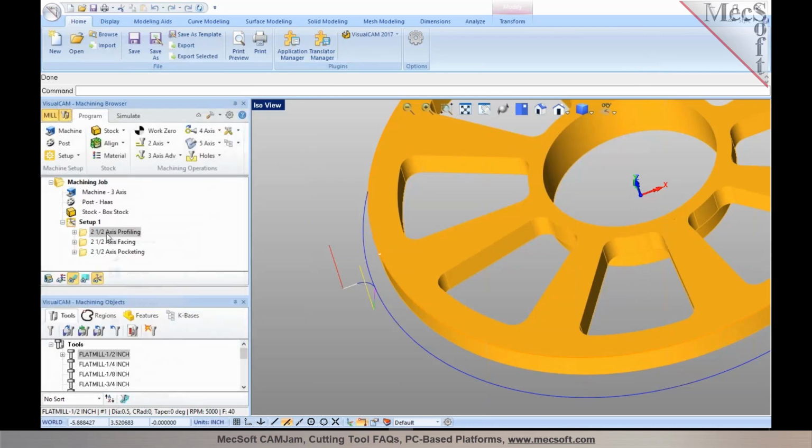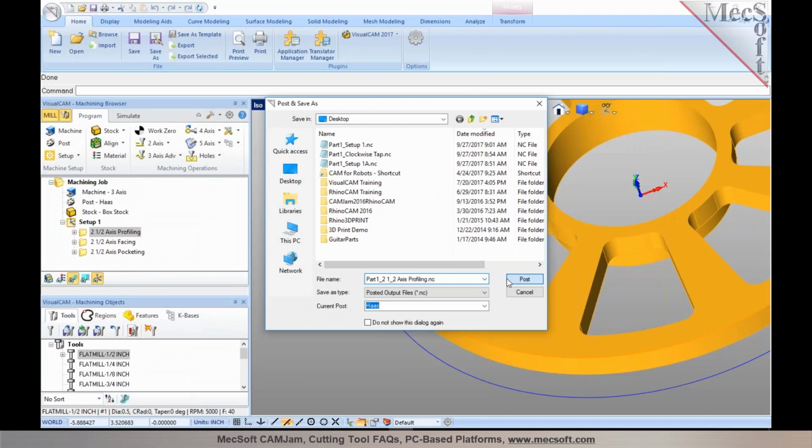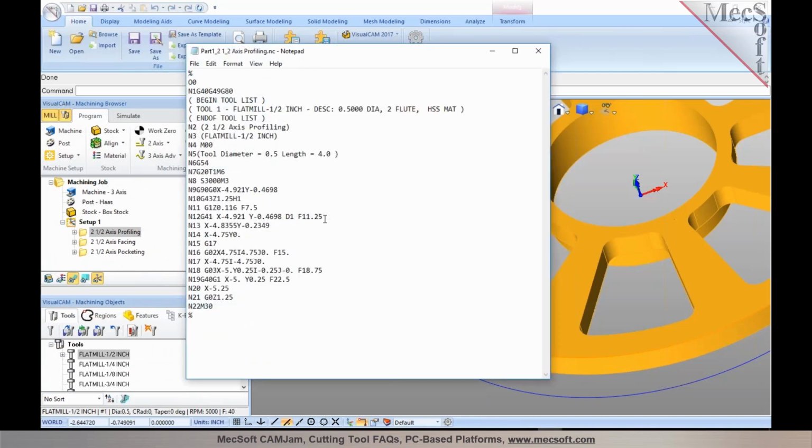post. And once you have those set, when you post process your machining operation in here, you will notice that it turns on the cutter compensation on the first linear move, and it turns it off at the exit motion. So this is how we can apply cutter compensation, and the value that you're trying to compensate for tool wear is entered in your controller's tool table. The toolpaths, however, are still automatically compensated by the tool geometry that you define for programming the toolpath. So what you're compensating here is for tool wear at the controller.